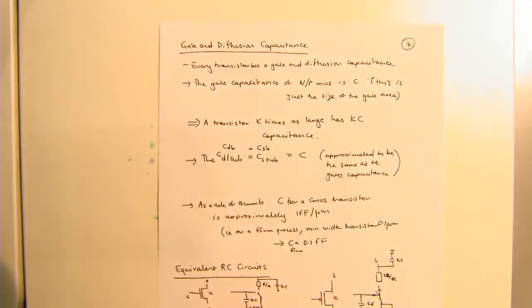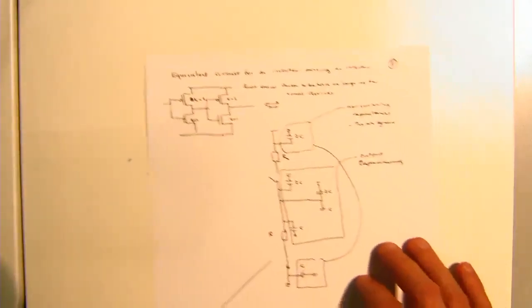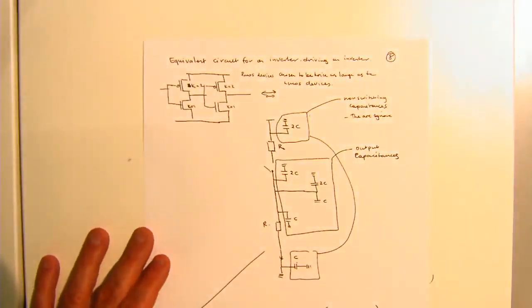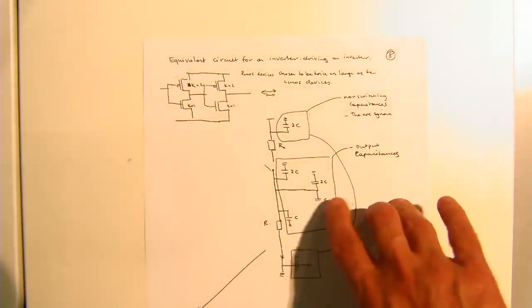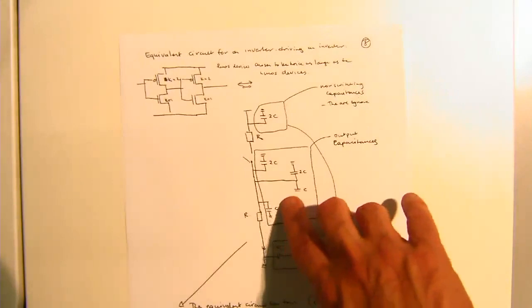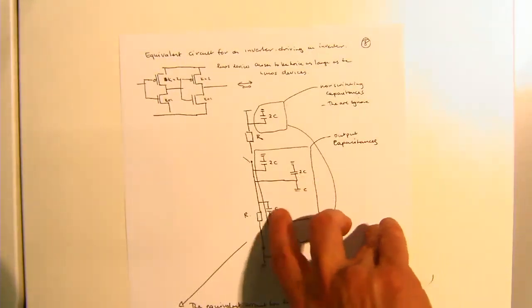Okay. We then went through various gate and diffusion capacitances, and we worked out how to calculate the gate and diffusion capacitances, making certain approximations. And there, what we said was, for an NMOS transistor, we assume that the smallest resistance is R. In this particular case, we're approximating a transistor as a switch, where it's got a resistance R and a capacitance at the various diffusions as C.